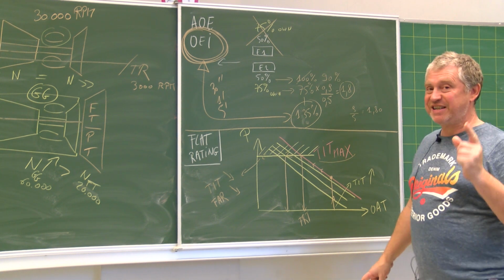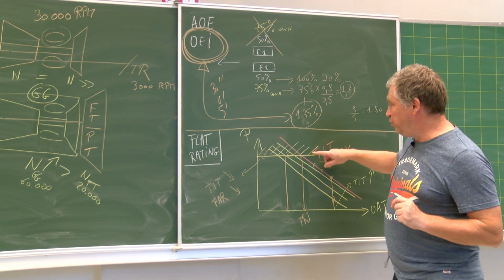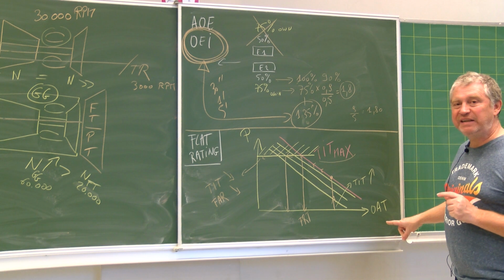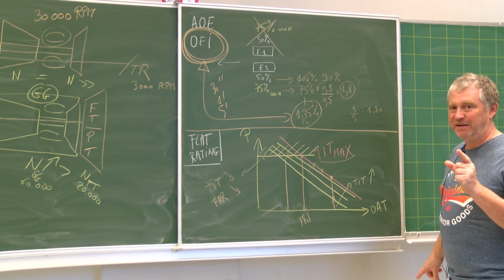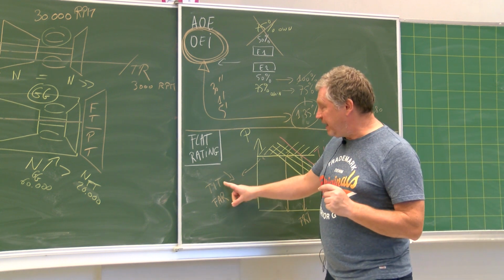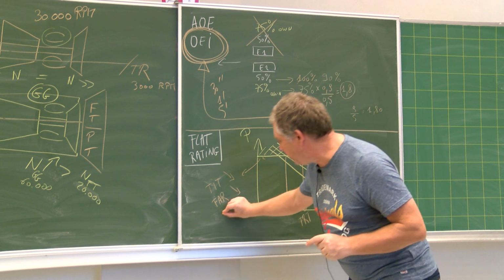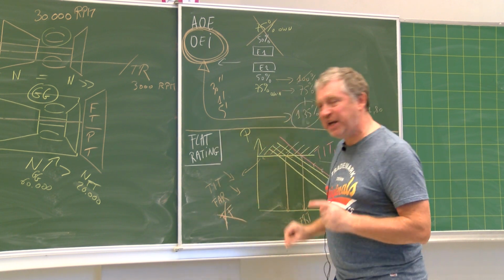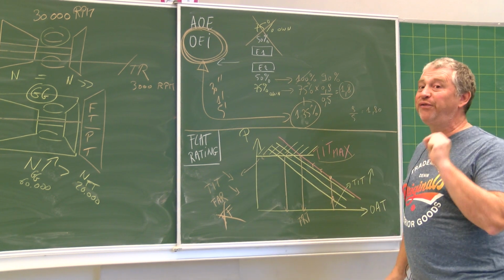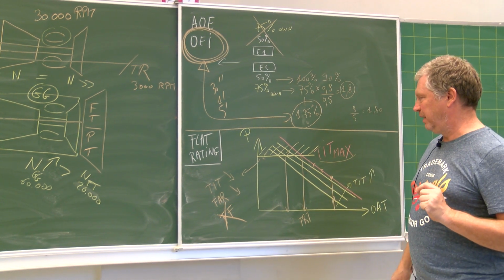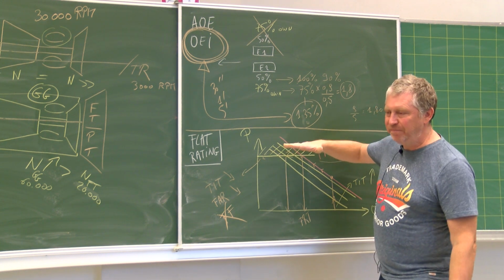I have not said that you are reducing the fuel flow, because when you move into this direction, OAT is changing, the mass flow rate of air is changing. And so TIT is changing, fuel-to-air ratio is changing. I have not said that the fuel flow is changing. I have just spoken about the fuel-to-air ratio. And this is what is called the flat rating.